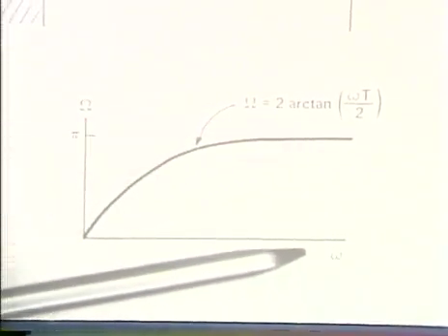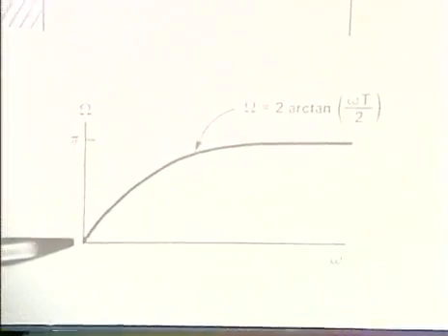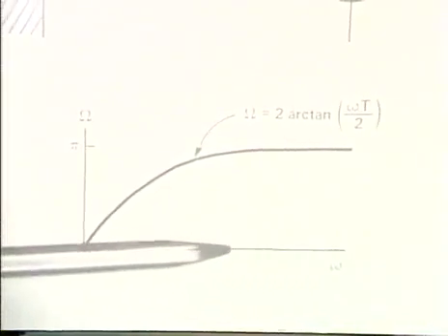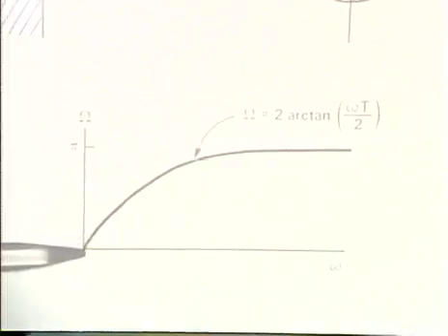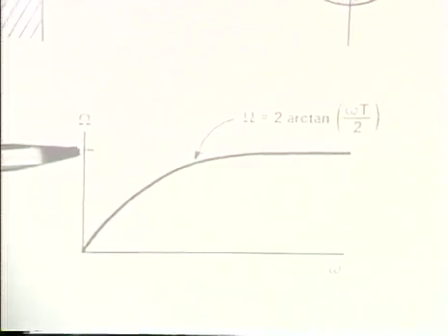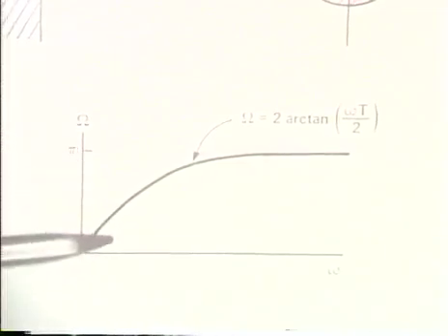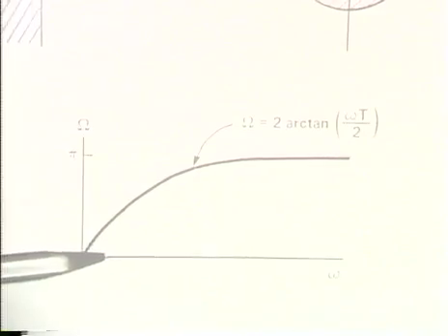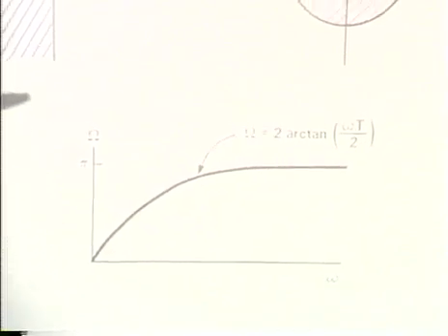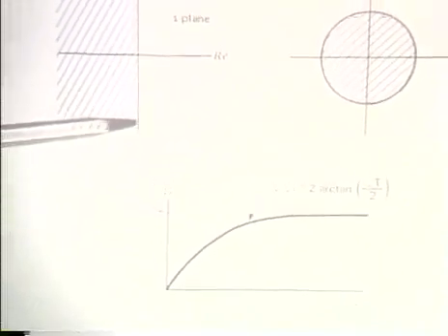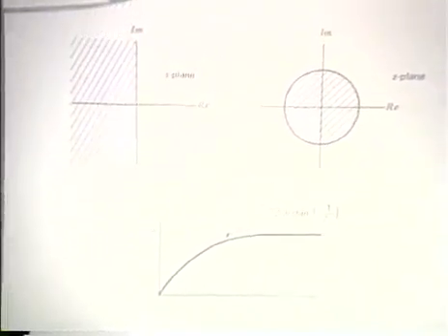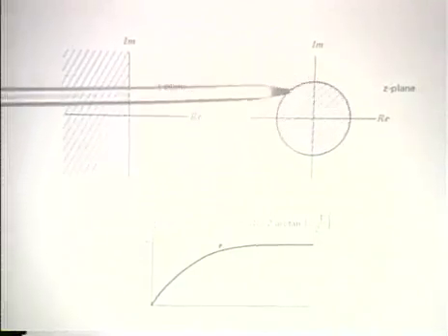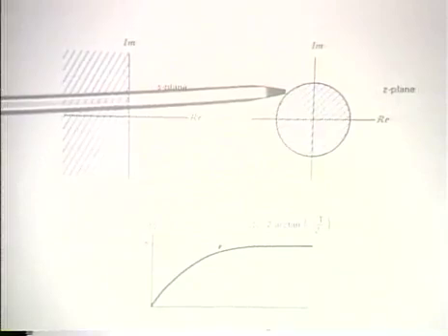And what this corresponds to then is a mapping of the j omega axis, or continuous time frequency, to discrete time frequency. And if we think more generally of the mapping represented by the bilinear transformation in the context of the s-plane and the z-plane, it corresponds to mapping the j omega axis in the s-plane to once around the unit circle in the z-plane.